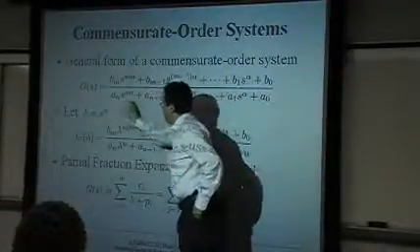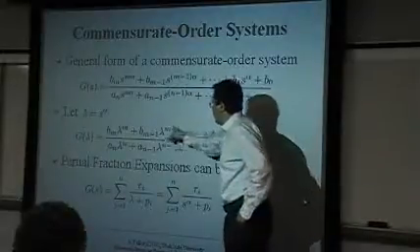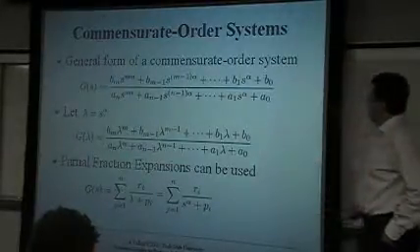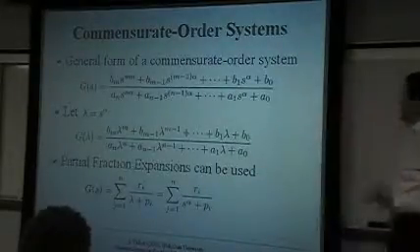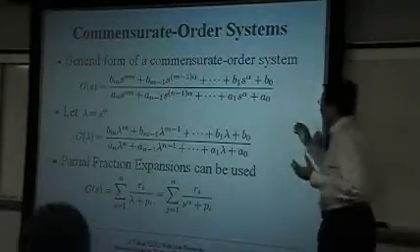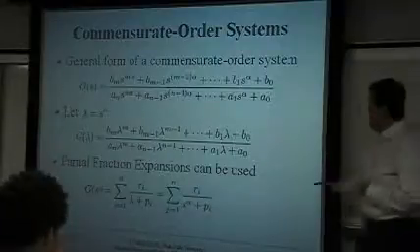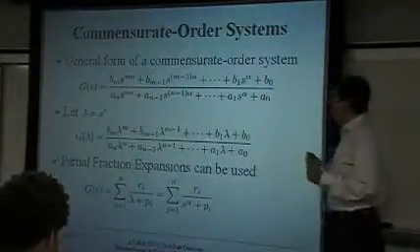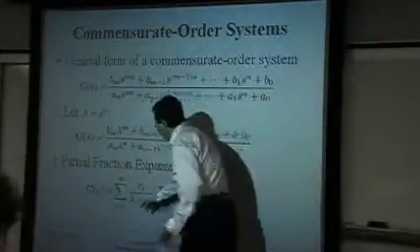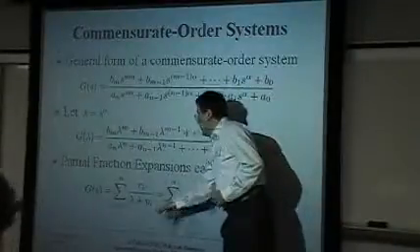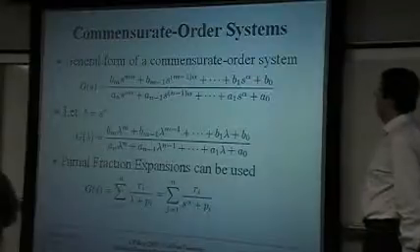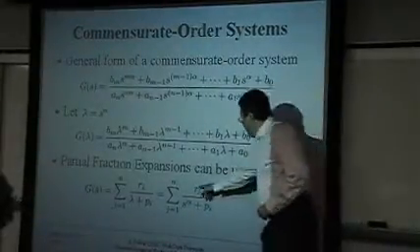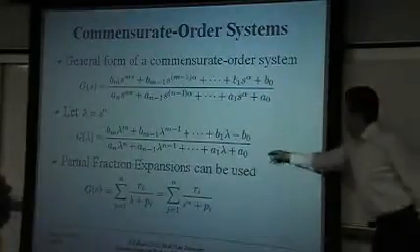If we have done this, we can easily rewrite the original transfer function like this, which is a standard rational function of the variable lambda. For this rational function, we can easily perform partial fraction expansion and find that the original transfer function can be expressed like this, if there aren't any repeated poles. However, if there are repeated poles, we cannot easily write it like this. So this is the limitation of the algorithm. And by the use of the Matlab function residue, you can easily find the R's and P's from this transfer function model.